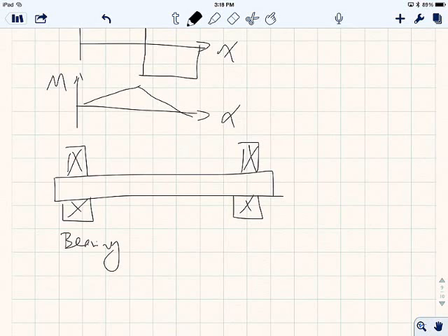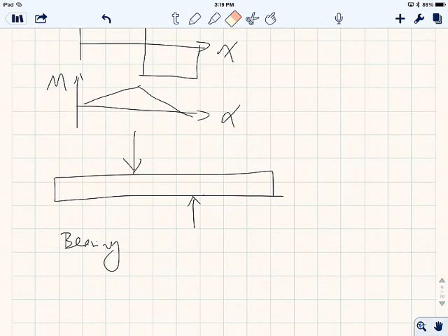Now, this shaft transfers power. So sometimes you use gears or pulleys, depending on what you want, right? Gears will transfer power. Pulleys will transfer power as well. We use a pulley on the outside. So when these gears engage with each other, there's just one concentrated force applied here. When the pulley transfers power, there's just one force applied over here. And then when you take the bearings away, all a bearing does is support force. Does it look familiar? Right?